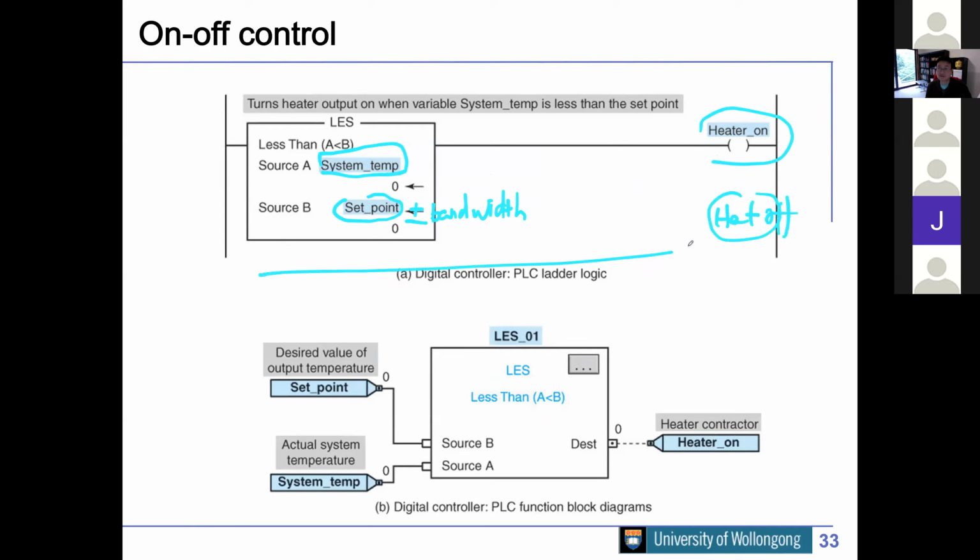There's another block doing the same thing. So one is plus, one is minus. Right? So that's a very simple controller, and this is basically just comparing two values. This block is actually a PLC ladder logic module. This is comparing two values, and this is your action. So this is what you connect to the output. Then normally that connects to a relay to switch something on or off. Okay, so this is the explanation of that block.